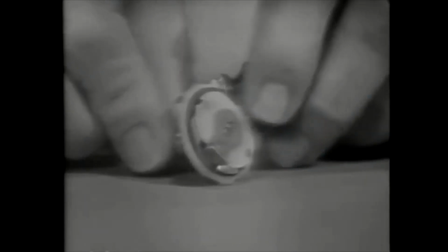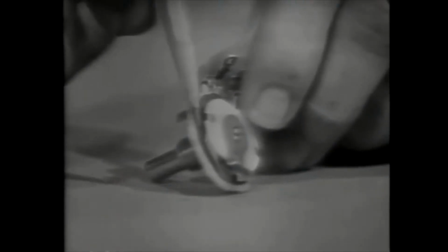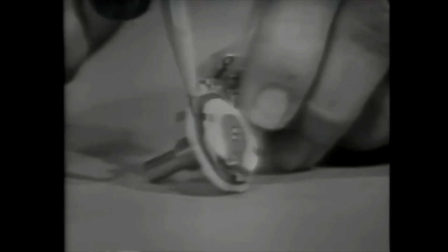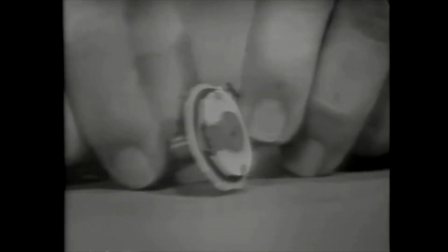Another common type of variable resistor is this one. Now, it's made of a carbon compound. It's very difficult to see the carbon compound, but it's down in here. It's a carbon disc. But again, by using this little contact right here, and by changing that contact, we change the length of the material being used, thereby changing resistance.